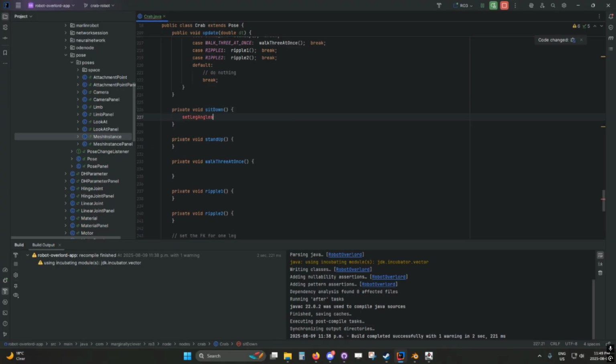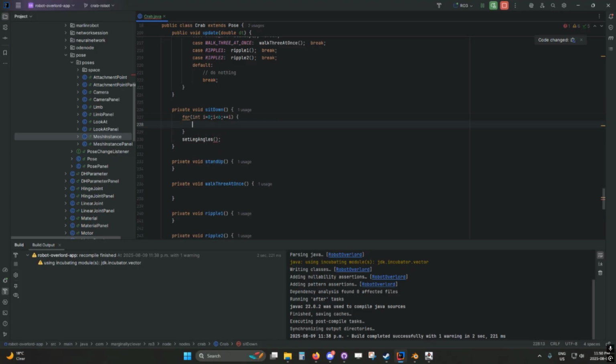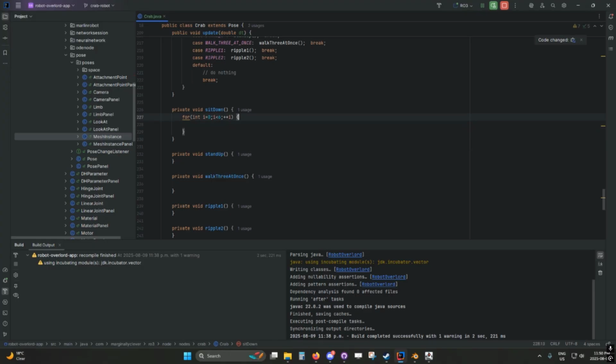A lot of people, I think this is how they do it. They use the inverse kinematics. So they give it a known XYZ coordinate, right? You're absolutely right, but we're not there yet. They're able to know where the toe tip is and you can do the intersection of circles, then you can find the location of the knee, and then you can reverse engineer the angles, and then you know exactly what to send to the forward kinematic system to get the motion that you want. Right.